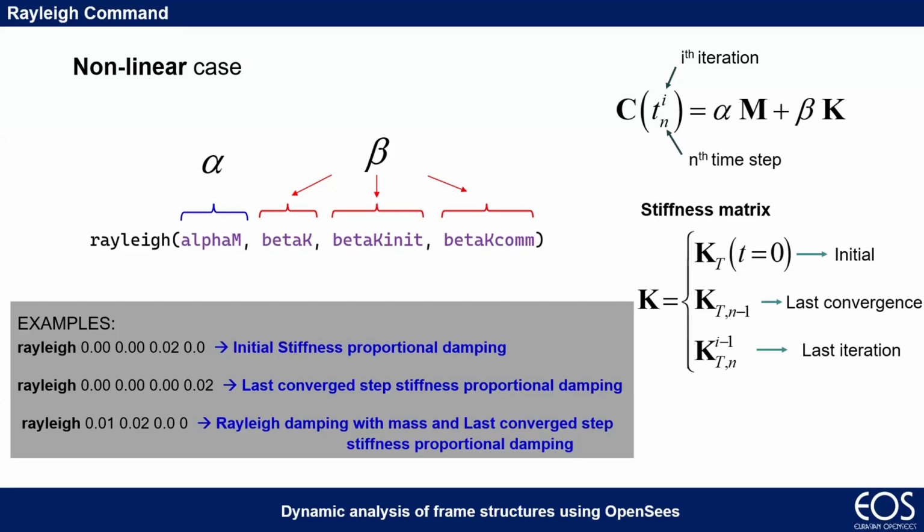But at the end of the last step, it wasn't softening, it was negative. So you have negative damping. I'll just repeat for the Zoom guys. So Dr. Petraka is suggesting that maybe it's better to use the initial tangent stiffness, right? Yeah, unless you know how the nonlinearity of your model behaves, since it is the most stable tangent stiffness matrix that you have during the analysis, right?